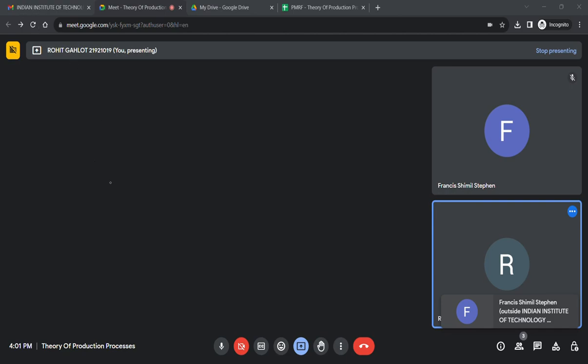And then there is one last thing. After that, we will start the numerical section. I just want to confirm that MR equals twice MC, or 1.2 times? 1.2 times. Okay, so it should be 20% higher than your casting modulus. You can see that the modulus of the riser is more than the modulus of the casting by 20%.